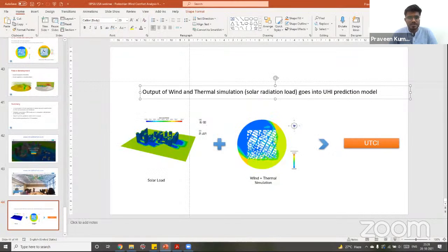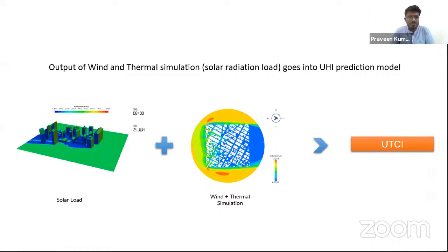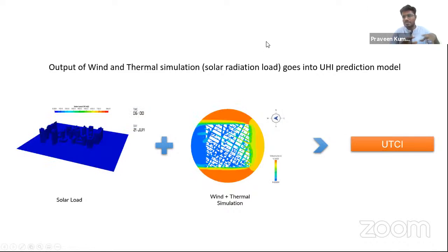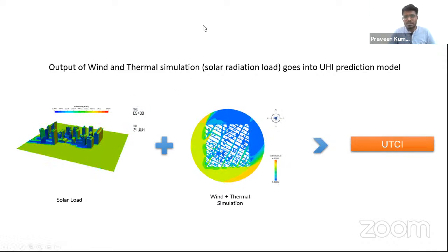Certainly. Okay. So as I was saying, this is the kind of work we are trying to do. For these buildings, we are trying to consider the outdoor solar irradiance, and then compare it with the wind and then form UTCI. So this is very much research, a work in progress. I just wanted to add this, and additionally for the guidelines about the meshing or the CFD setup, you can refer to COST Action 732. That is the best practices guideline for such wind analysis. So COST 732.